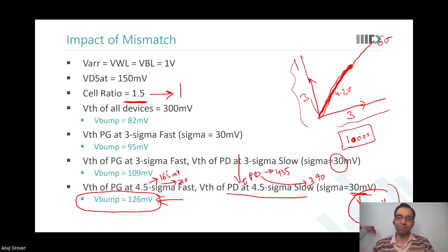So you will see that typically the on-chip memory capacity, including L1 caches, L2 caches, and so on, of all the cores and of the remaining part of the chip, for digital SOCs, is actually very high. It could be 64 megabits in the most advanced technologies today. So 6 sigma is the bare minimum that you need to qualify for SRAMs.